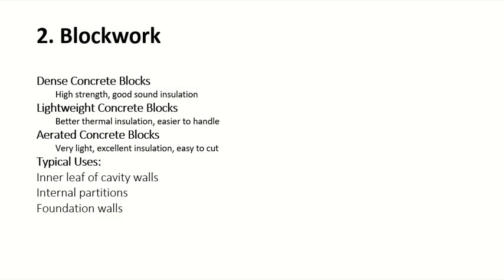We have different types of concrete. We have high strength concrete, normal strength concrete. We have talked about blinding as well, if you remember, which you put under the foundation and under the wall. That is also a type of concrete, but that is very weak. So all those types of concrete can have their blocks, right? The blocks can be dense, lightweight, or aerated. Aerated is very good for the walls.